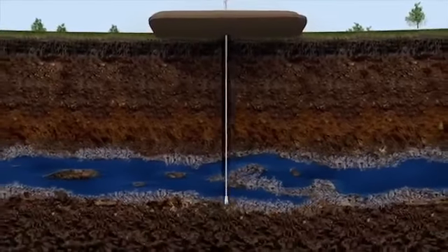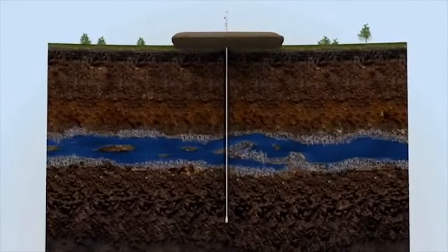A hole is drilled straight down using freshwater-based fluids, which cools the drill bit, carries the rock cuttings back to the surface, and stabilizes the wall of the well bore. Once the hole extends below the deepest freshwater aquifer, the drill pipe is removed and replaced with steel pipe, called surface casing. Next, cement is pumped down the casing. When it reaches the bottom, it is pumped back up between the casing and the borehole wall, creating an impermeable additional protective barrier between the well bore and any freshwater sources.